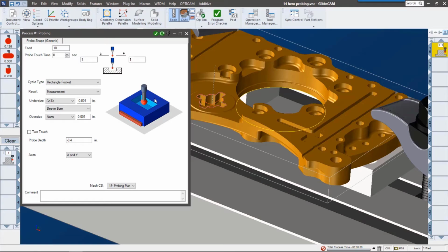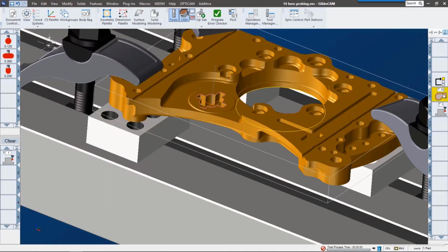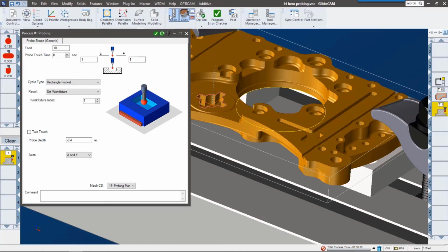And what these are is they're targets. And I've kind of pre-baked this a little bit. If we look over on the right, you can see I have a go-to move, and then there's my contour. So I'm going to say go to the sleeve bore, again, here's my target, and then run the program from there. Let's go ahead and check this out in simulation.